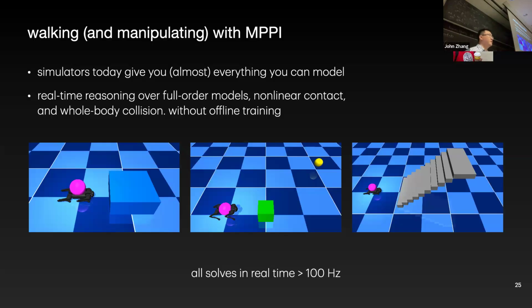Versus on the CPU, if I'm only simulating tens of samples, I can do this on an Intel i9 machine from the last couple of years, not even the best of the best. We're looking for something with fast single core performance, with, let's say, 20 cores, and that gives us 20-30 samples at over 100 hertz. It turns out in my experience that I would argue that's what you want.